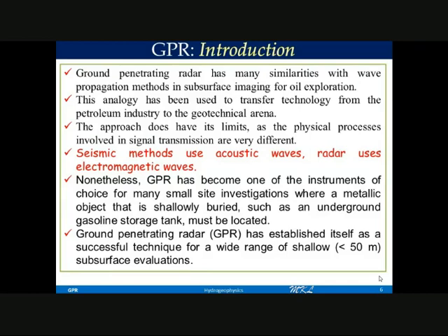Topp's paper is a very old paper, but it is still applicable for GPR signal or GPR data modeling, where you want to model the subsurface moisture content.